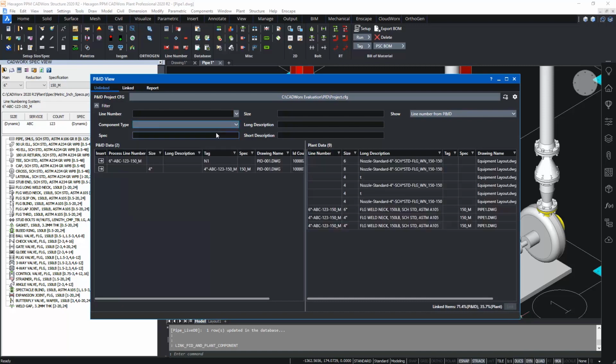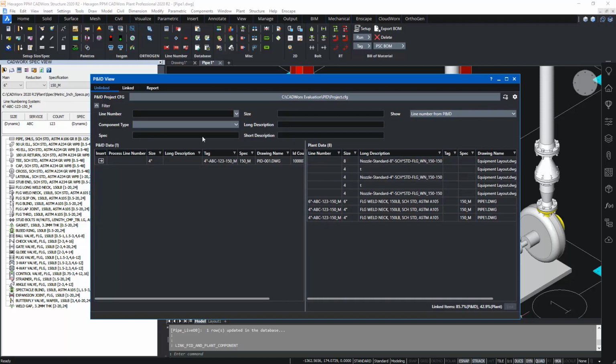So that's all the valves, all the reducers. There are a couple of items left. There is a small 4-inch section of line in the P&ID, which I'm not concerned with, and there is the nozzle N1 attached onto the vessel, which I know is this nozzle. It's the only 6-inch nozzle that I have in the model. There's an 8-inch nozzle on the vessel, there's a couple of 4-inch nozzles of course on the pumps, and I'm going to link N1 with the 6-inch nozzle. I'll link those two together as well.